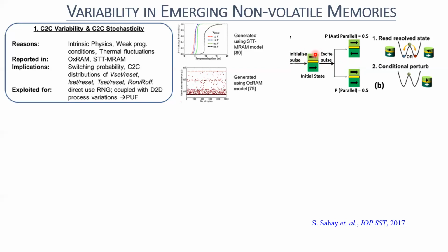One of them would be a pinned layer, where the magnetic moment of that layer cannot be switched, which in this case is this one. However, one of them would be the free layer, whose magnetic moment or magnetization can be switched. So if it is in this direction, by passing a spin polarized current through this layer, or by applying a spin orbit torque or spin transfer torque, you can change its orientation in the opposite direction.